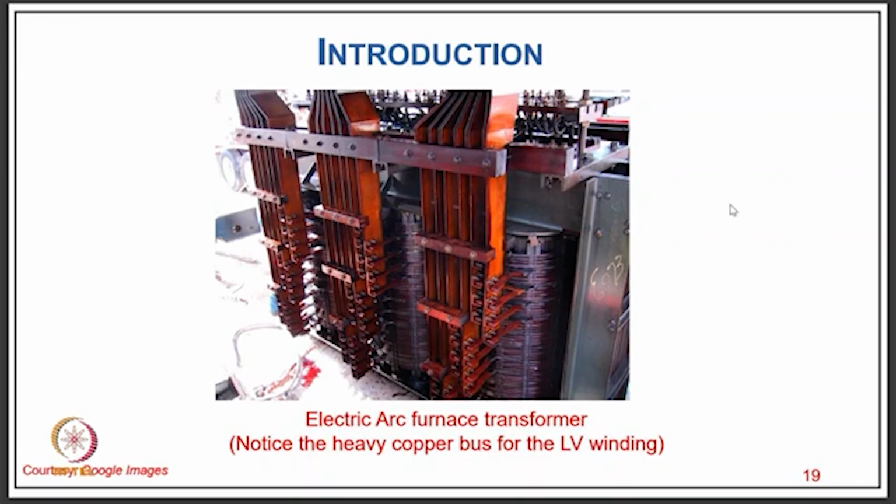or even lower than that, such a large single-phase load we cannot connect directly to the three-phase supply system. So certainly we have a special arrangement of these furnace transformers for this purpose. The purpose of those transformers is, number one, isolation, and number two, to convert the supply from three-phase to single-phase. But when both the furnaces have almost equal load, it behaves as a balanced load on the three-phase supply system through this transformer arrangement.